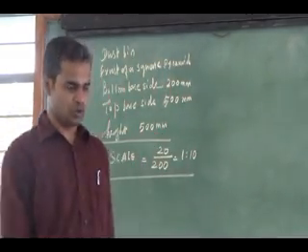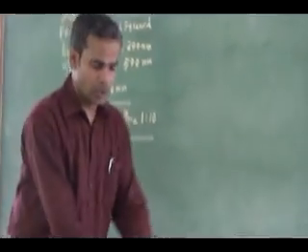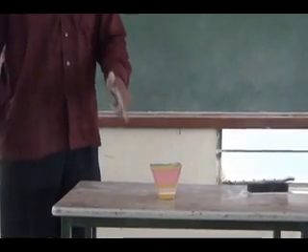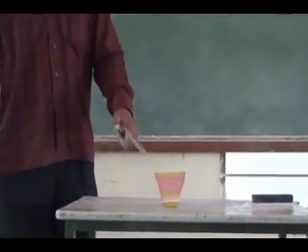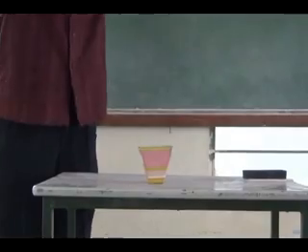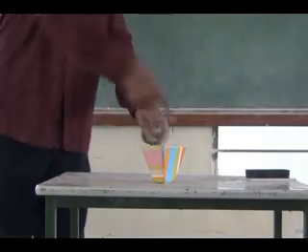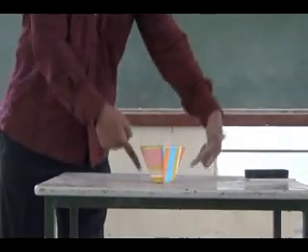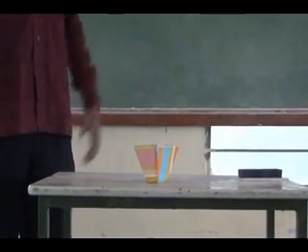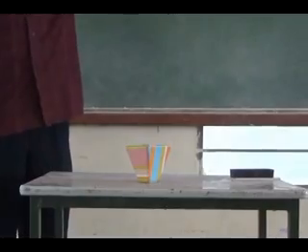Suppose I keep it like this. Do you have a true slant length? Look at this dustbin. Suppose I keep it like this, parallel to you. Can I directly get the true slant length? At 45 degrees, it's nothing but the slant edges, and none of these slant edges will be parallel in this orientation. If I keep it like this, the two slant edges will be parallel, so directly in my orientation I can get my true slant length. It's up to you. You can draw it in any orientation, you can rotate it, and you can get a true slant length.